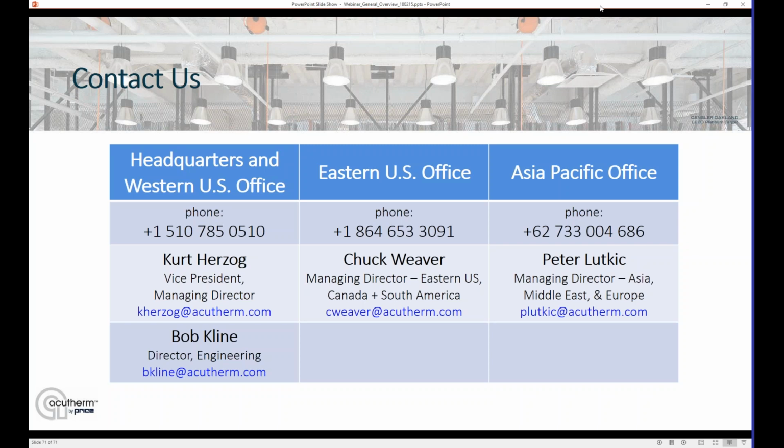Also not a great application for Therma-Fuser diffusers. But if you've got, say, a medical office building in contrast, where you've got a lot of small spaces, doctors' offices, exam rooms, that's a great application for a Therma-Fuser diffuser system. So really anywhere you're thinking VAV, think Therma-Fuser diffusers.